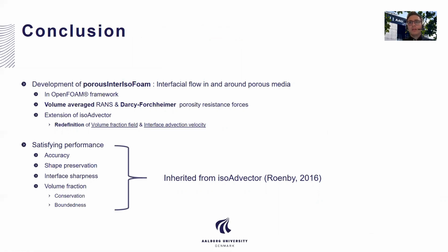This presentation was about our recent development, namely porousInterIsoFoam, a solver capable of simulating interfacial flow in and around porous media. The implementation was carried out in the OpenFOAM framework. And for this development, the volume-averaged equations and the Darcy-Forchheimer equations were employed.